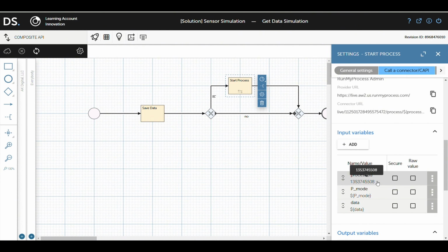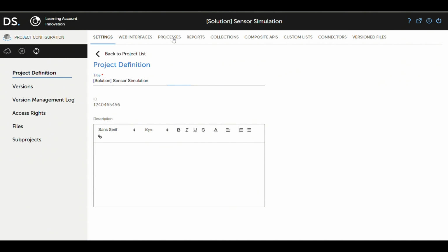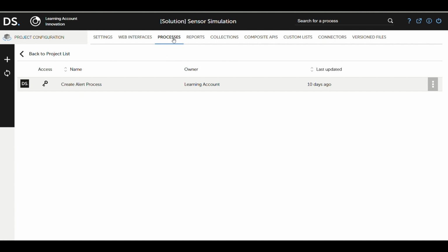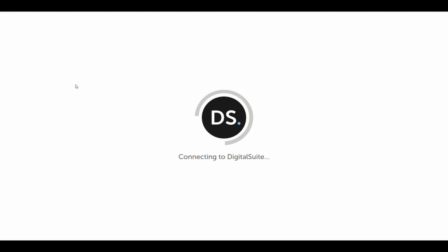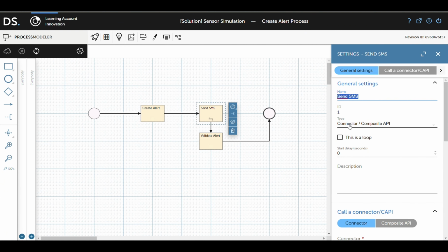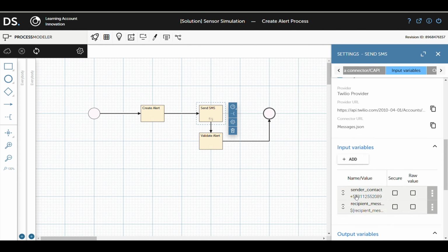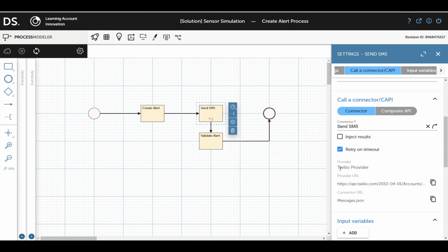Here, by the process ID, we are integrating an alert process where, if the variable measured by the sensor exceeds a predefined limit, a text message is sent to the registered phone number. Additionally, these alerts can also be sent via email to notify relevant personnel or trigger commands to physical actuators that provide an immediate solution to the situation. For instance, the system could activate a cooling fan, close a valve, or adjust machinery to address the issue in real time.